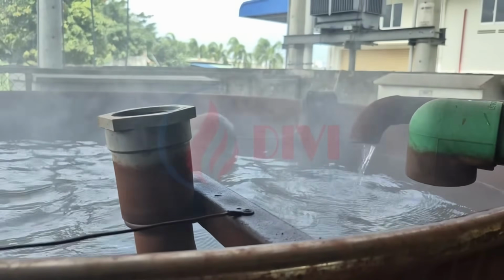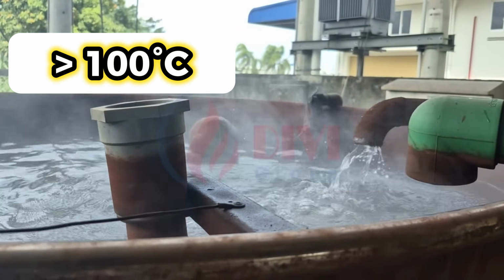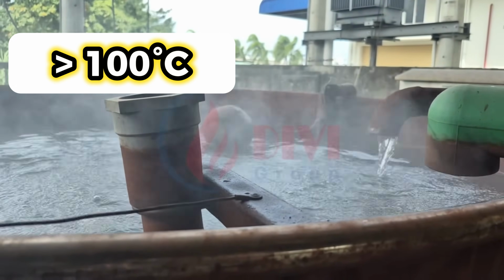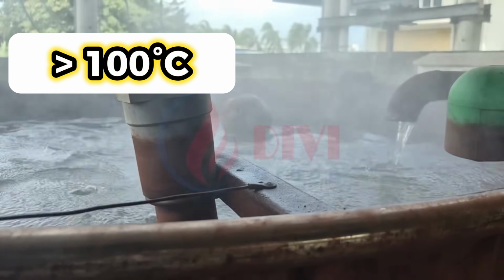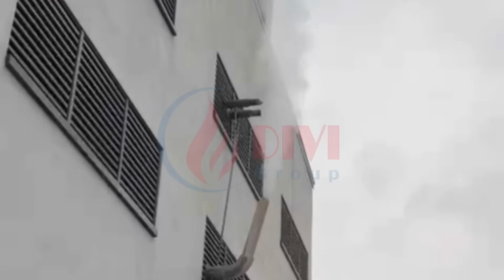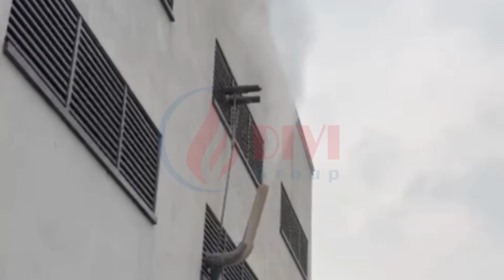However, it is still very hot, often above 100 degrees Celsius, and still contains a large amount of energy. When this hot condensate is discharged into an open tank at atmospheric pressure, part of it flashes into steam and escapes. This is where energy loss occurs. So how significant is this loss?